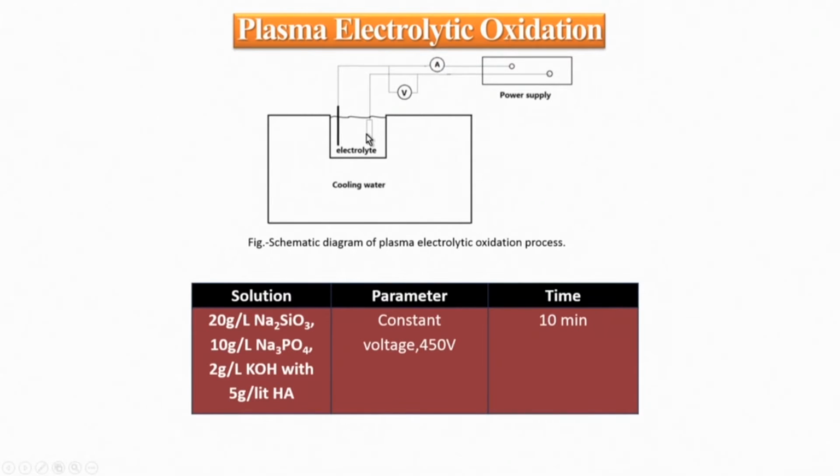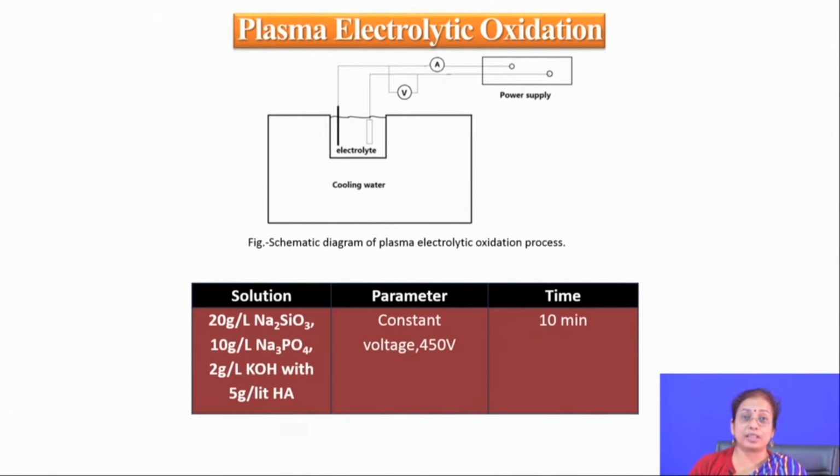So, this is the process which is shown here. You take your component as the anode, and you can use stainless steel as the cathode, or any other non consumable material like graphite. You have a very high voltage power supply unit attached to the cathode and anode, and this is AC. Whenever the current is on, there will be formation of oxide scale and then its breakdown, high resistance region generation, subsequent melting of the underlying metal and its transportation to the surface.